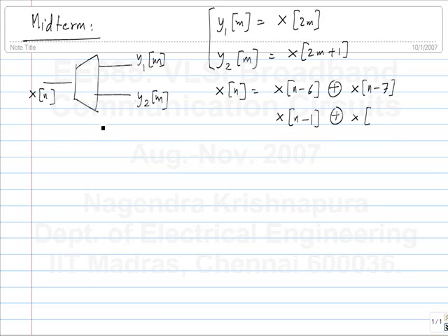For PRBS N, if you have the last tap N1, then N minus N1 and N also give you the pseudo-random sequence, but in a different order. It's a time reverse version of the same pseudo-random sequence. But anyway, the idea is to prove that it will fall into one of these categories, right?